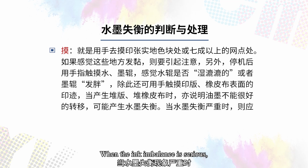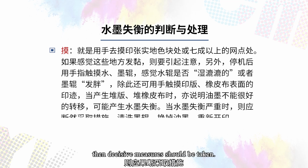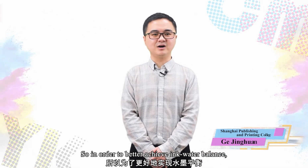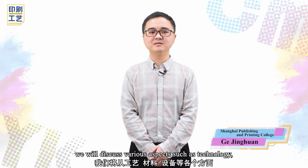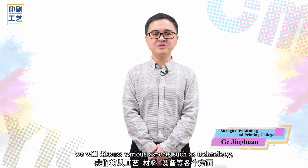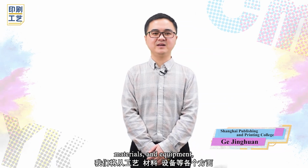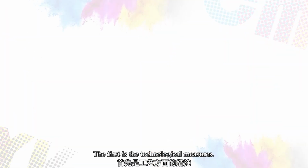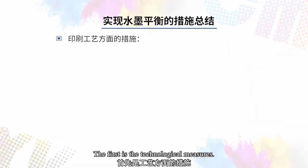When the ink imbalance is serious, then decisive measures should be taken. Clean the ink roller. Change the ink. Restart printing. So in order to better achieve ink-water balance, we will discuss various aspects such as technology, materials, and equipment, and take reasonable measures. The first is the technological measures.